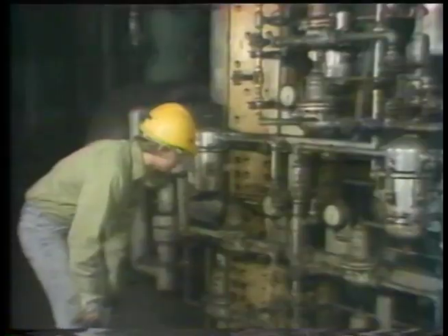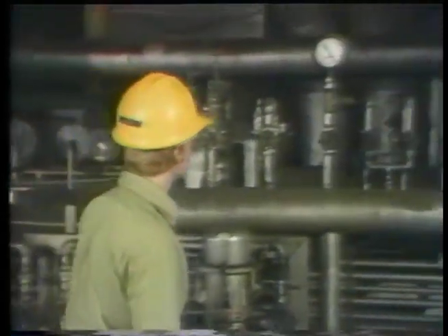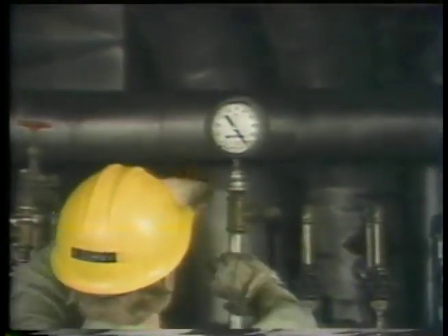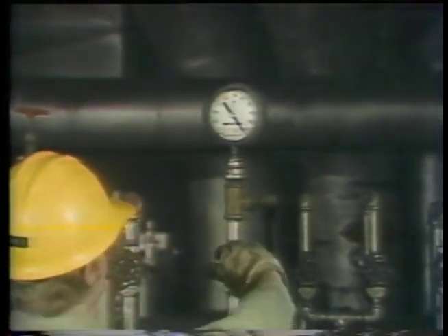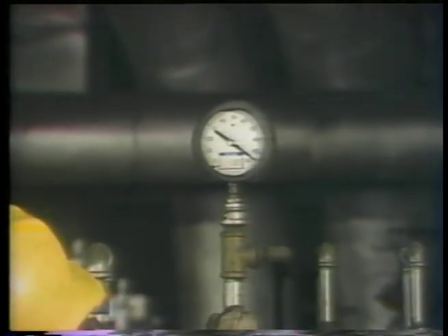Now, the first example of instrumentation problems that we're going to look at, you probably won't find very often. It's a gauge that is off scale. While this is not a common problem, if it occurs, you need to recognize what to do about it. You'll know this has happened when you see the pointer at full scale or up against a peg on the scale face. If during your routine checks of the instruments in the plant, you find a gauge that is continually showing maximum pressure or is off the scale entirely, your first action should be to isolate the gauge from the system. This is usually done by closing a valve on the supply line.